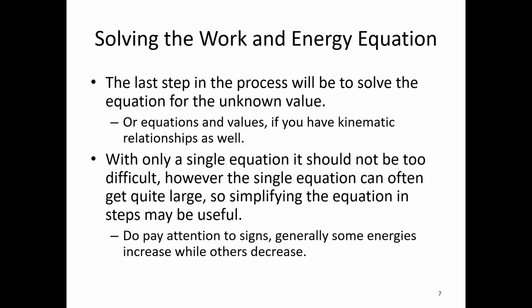With only a single equation, it should not be too difficult. These are not vector equations. These are just scalar values. However, a single equation can often get quite large, particularly with these rigid body problems where we have things like translational and rotational kinetic energies. So simplifying the equation in steps may be useful.